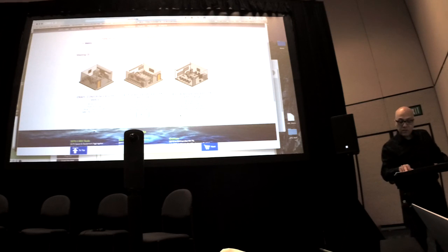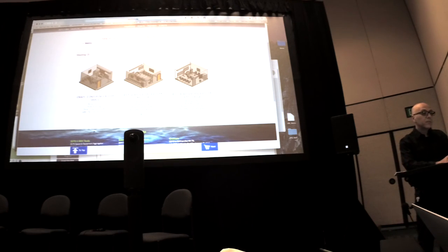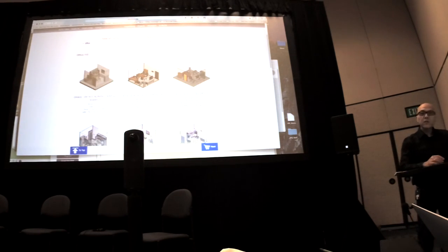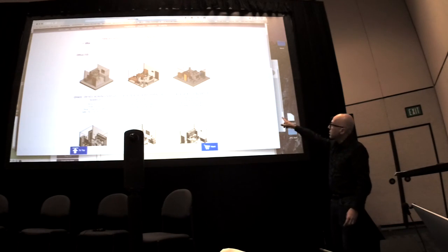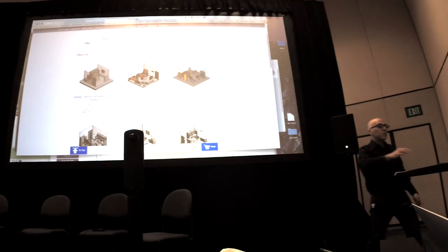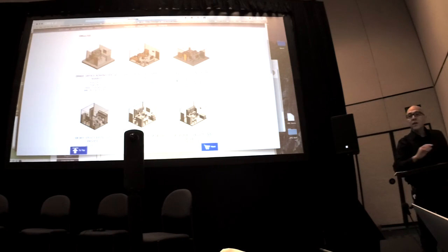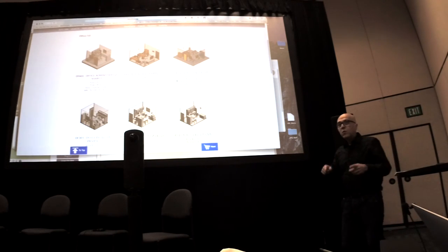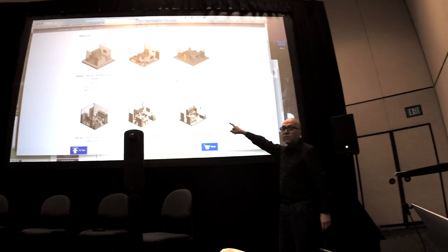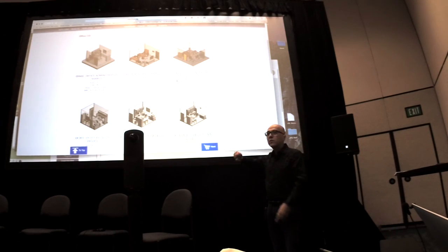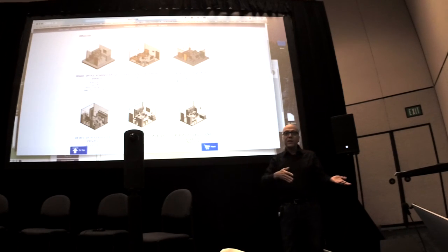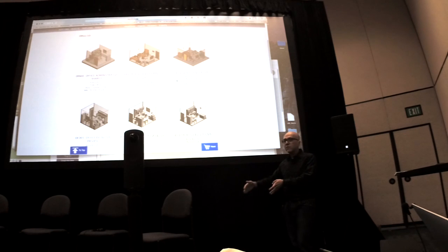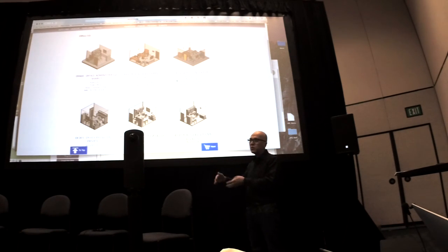Next one off is office. So if I search office or the code, we're all used to this kind of search, right? You start typing in code, the code letters or the name of the thing or the square footage or whatever, and starts coming up with things that are available. Now, if this owner this morning decided to change the requirements of that conference room in their database, it would actually show up here as I searched it, and it would download the right data that goes into the BIM. This is real-time access to the owner's knowledge base of what they think a good hospital should be put together as.